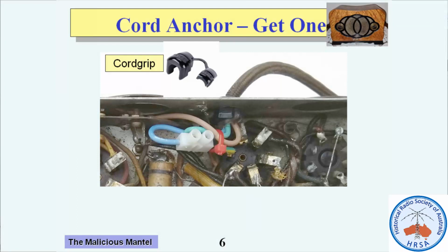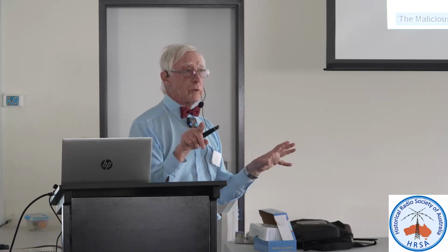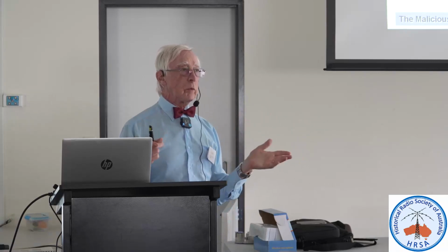the leads break out immediately inside the chassis. You can use a grommet and a chassis clamp. That works fine, but then you've got an amount of cable that you can't really pick apart and route anywhere inside the chassis. If you've particularly got a tight chassis, then that's the ideal solution, because as soon as it comes in, the leads part out and you can dress them to where you need. They're available from JCar and heaps of other places. I strongly recommend that that's your method of preference.